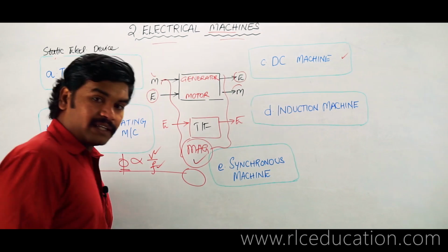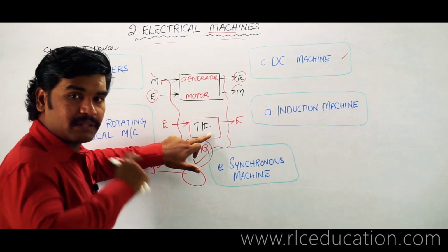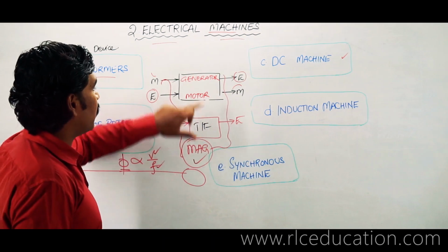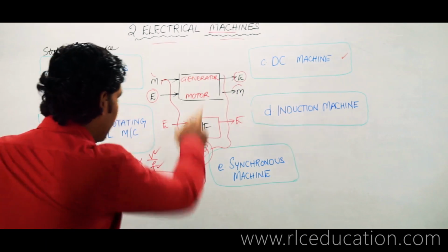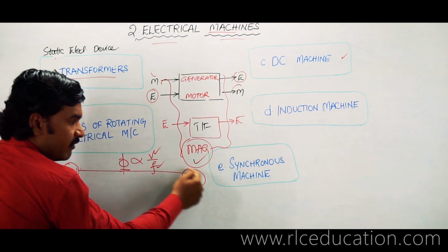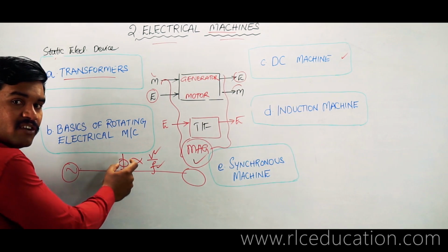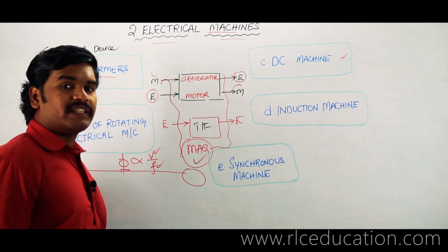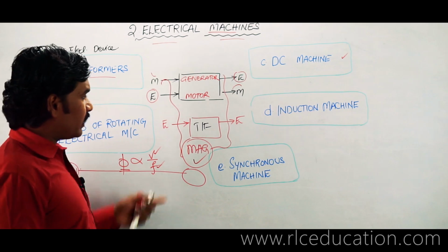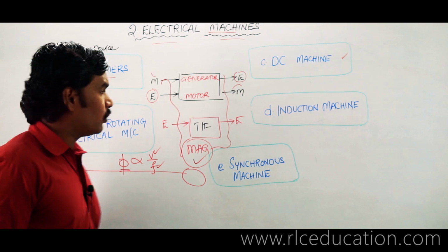So do you think, and tell me, what does this transformer, which is the important part of the power transmission system, as well as the motor, which is the majority of the load connected to the power system, depend on? It depends on the quality of the magnetism maintained inside that machine, which is nothing but the flux, which in turn depends on voltage and frequency. If your voltage and frequency are not properly maintained, do you think the entire power system will operate in a satisfactory manner? No, you don't have that case.